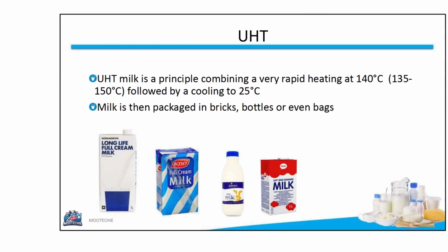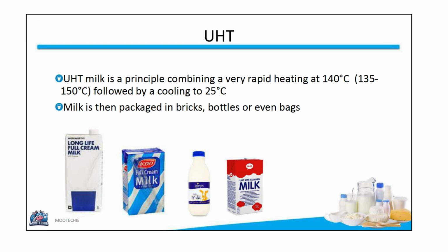The principle combines a very rapid heating of milk to a temperature between 135 and 150 degrees Celsius, typically around 140 degrees Celsius, followed by an equally rapid cooling down to about 25 degrees Celsius. This treated milk is then packaged aseptically in bricks, bottles, or bags.